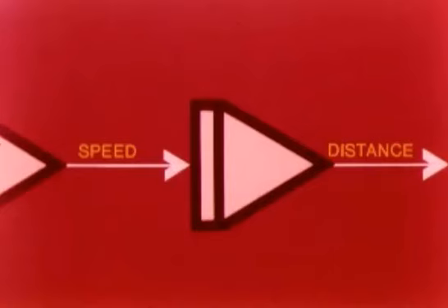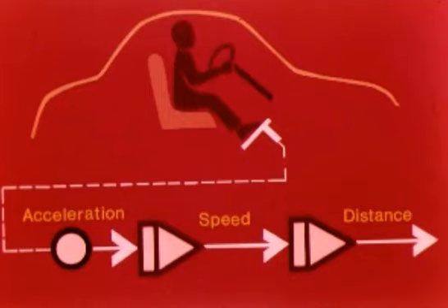In the block diagram, a voltage representing speed enters the input of the second integrator. As we have seen, the output is a voltage corresponding to distance. This could be connected to an odometer to indicate distance traveled. Thus, we have simulated an automobile. It can be started, stopped, and driven at a variety of speeds. We have made provision for the driver to continuously monitor speed and distance.